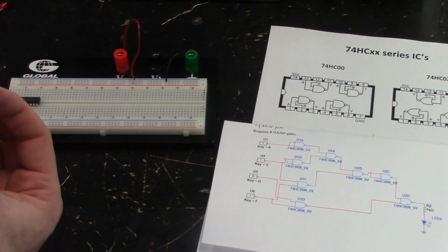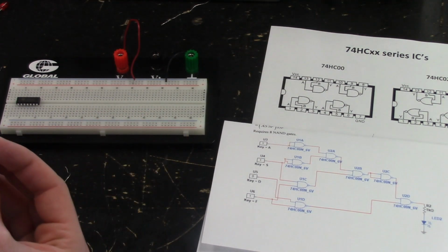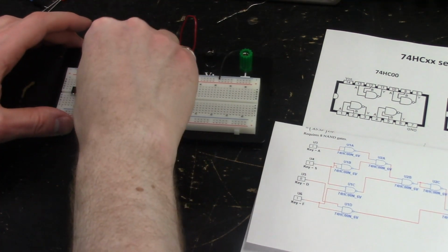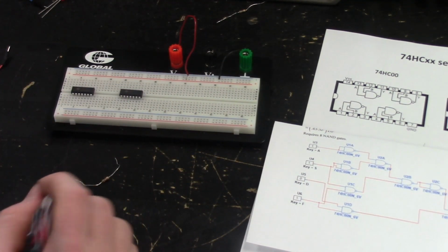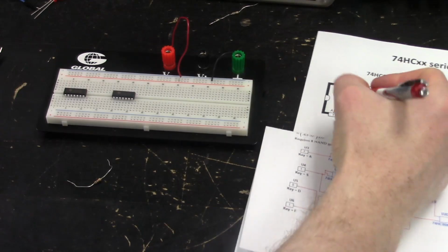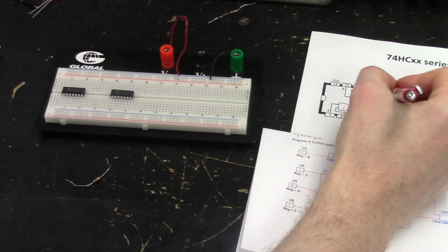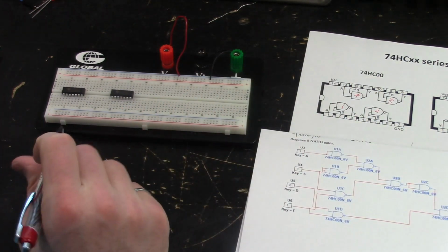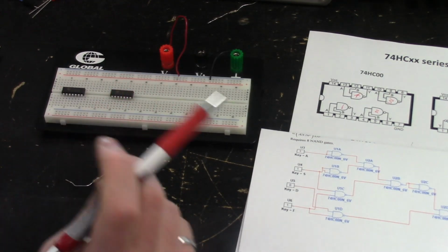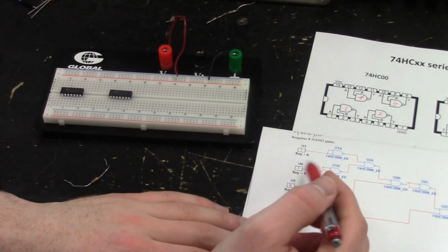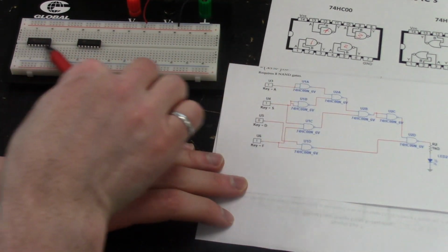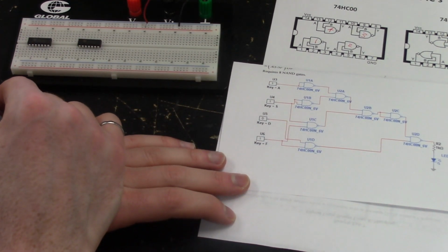putting the little indicator, the little divot, facing left, just to keep things straight on which way is pointing which way. And now, to remember which one is which, we can go around like 1, 2, 3, 4 around the chip, and then just label them over here to decide which gate should be where. So let's see, considering what needs to be connected to what, it's probably simpler if we have everything generally going from left to right across this chip.